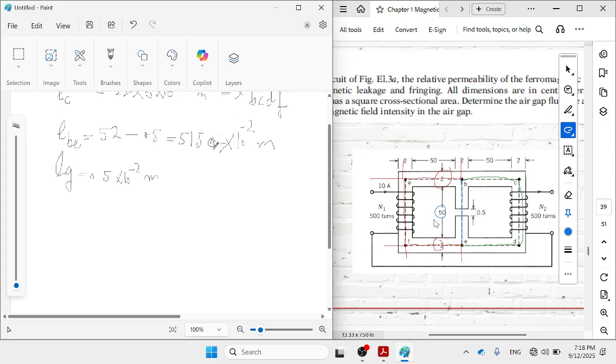Okay, if I'm going to represent the magnetic circuit in the form of an electrical circuit, we have to convert this part to a voltage source, which we call MMF, or magnetomotive force number 1. Using the right hand, all fingers except the thumb in the direction of the current, the thumb will give you the direction of the flux. So we can represent it as positive, negative, correct?